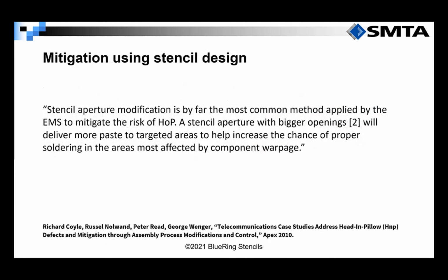So let's discuss some stencil modifications for head and pillow mitigation. As we've discussed, one of the easiest solutions is to modify the stencil aperture design. This process can be done quickly and is relatively inexpensive, and the stencil can be replaced in a day or so if needed. In many instances, the head and pillow defect may not be expected, and a new stencil may be required to address and possibly correct the defect quickly.